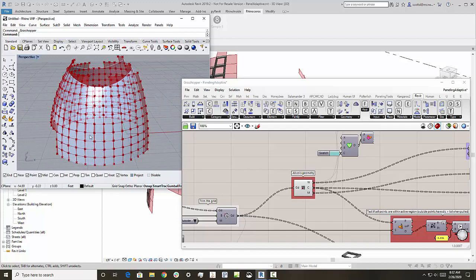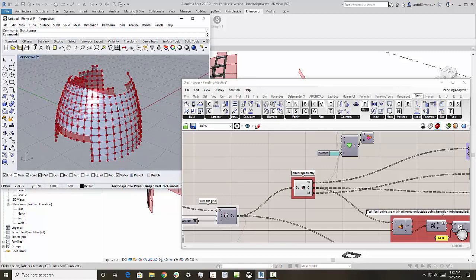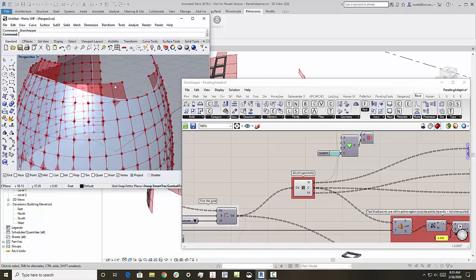And this could be a poly surface. It could be a series of solids. It doesn't necessarily only have to be a surface. Anyway, now we can have some fun with Grasshopper, because Grasshopper can select and filter these different conditions. We can do one thing with internal panels, for instance, ones that are fully encased in the original surface. And we can do different things on the borders and the edges, as our full quad rectangular panels maybe break down based on what's happening at this edge here.